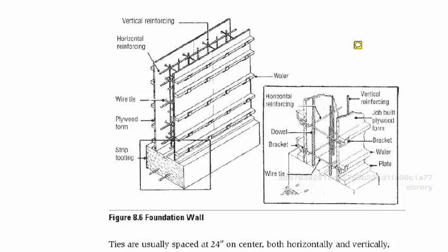Again, once you have the footing in, and then you're putting something on the footing, whether it's a column or a wall of some sort, the interior of a fountain, for example, you need to build some forms. And you're generally going to have plywood or large wide planks. You're going to have ties. You're going to have different amounts of whalers to hold the forms in place. And inside the forms, you're going to have some reinforcing bars to provide strength. So again,